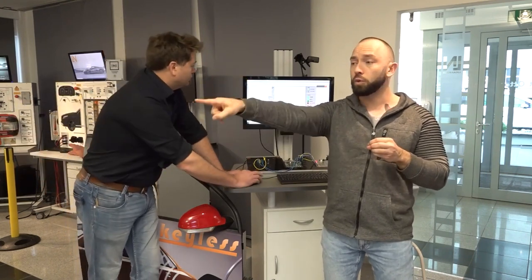And CAN bus doesn't have a master-slave system, so in CAN bus, each CAN node is a master basically, because there are other basics of how they are talking with each other, so that they are not talking at the same time. So this problem has to be solved. At the LIN bus system, you do it with slave and master. And as long as you're not the master, you cannot send anything on the bus. And this is why you're using LIN at the side mirrors, for example. As the master is hidden inside the car, you cannot access it. But when you would use CAN there, you can easily get access to the CAN network from the outside.